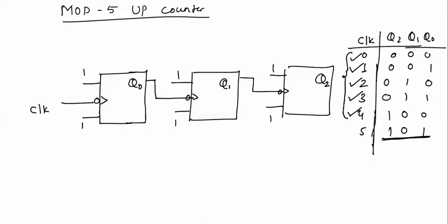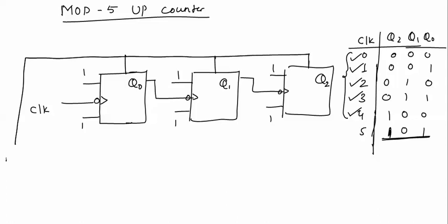So to reset the flip-flops we will have to design or employ one more signal, which will be called reset signal. If we have logic 1 at this reset signal, all the flip-flops will be resetted again to 0. To have logic 1 at this reset signal, we will have to derive this signal from the flip-flop output itself.